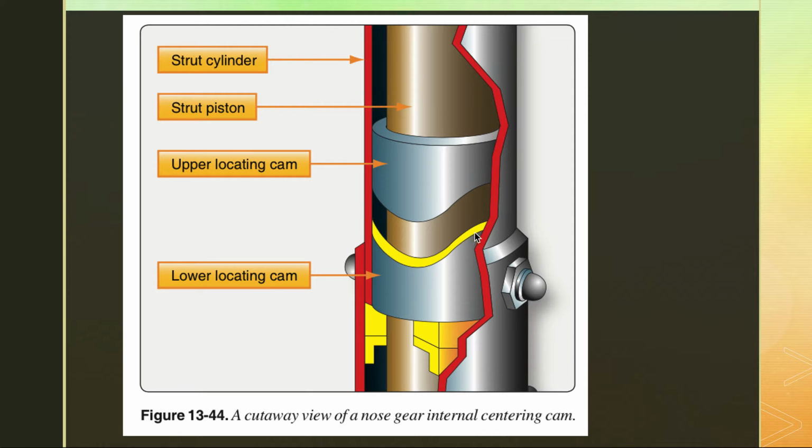This is not something you can see and you can pre-flight, but know that you should have that wheel straight when you take off, and if it's not quite straight, then there's a centering cam inside the strut that does it for you. Probably more applicable to helicopters who could stop and have the wheel crooked when they take off, and as I've actually had that happen in the military, and we had to break a few components to get things safe on the ground again. So the centering cam works unless the wheel's too crooked when you take off.